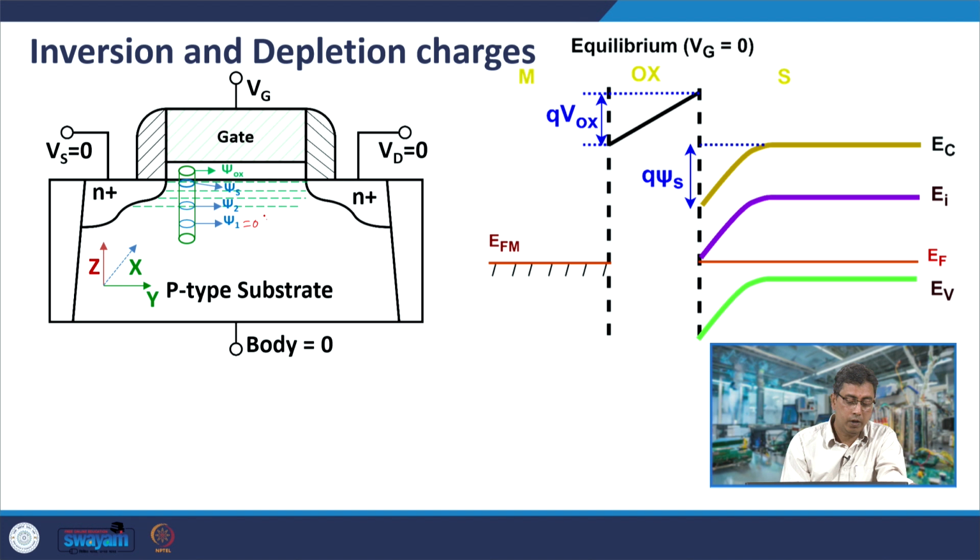If that is our 0, then as you get into the depletion region upward, that is in the positive z direction, you would observe that the electric field should keep on increasing, because if you take this Gauss cylinder, then as you move upward from this point, that is where the depletion region begins, you keep on taking this lid up and see how much charge is there within this Gauss cylinder below the top lid. You would observe that the depletion charge would get accounted in it, depletion charge below the lid.